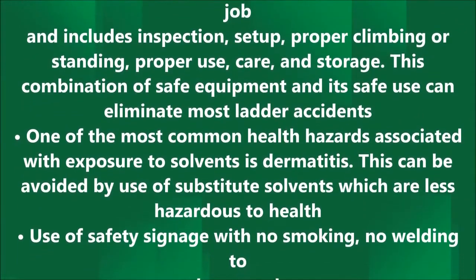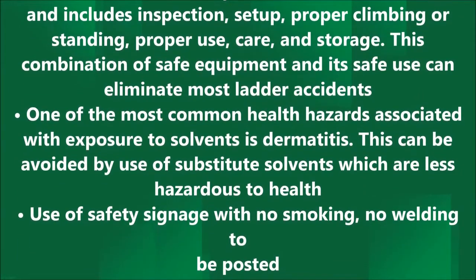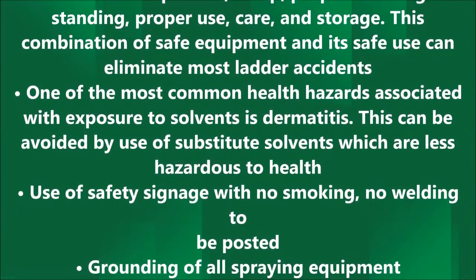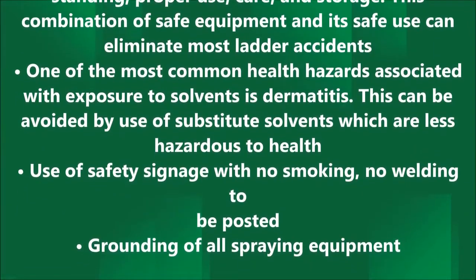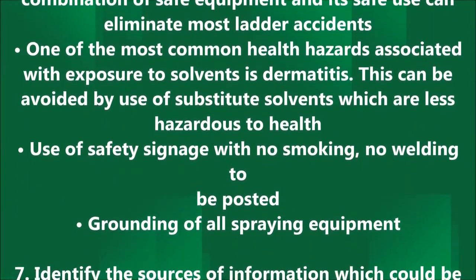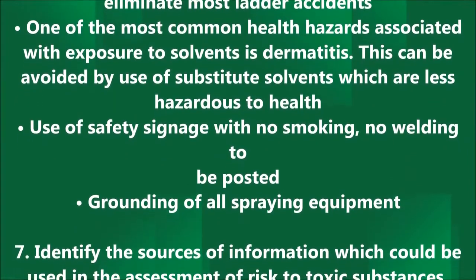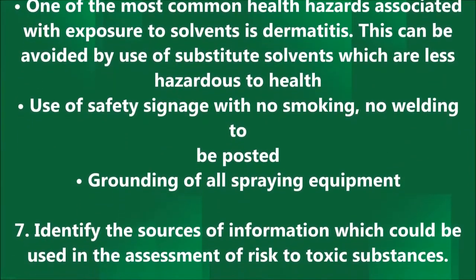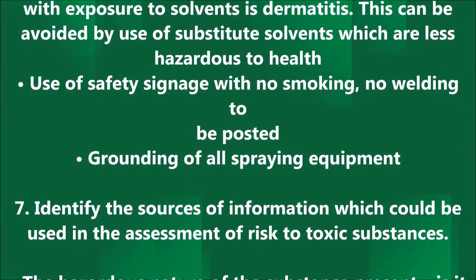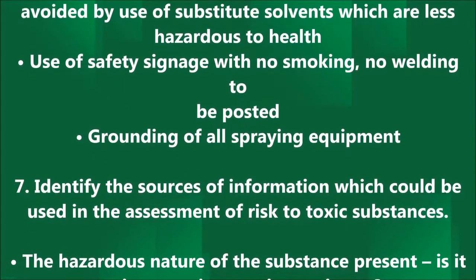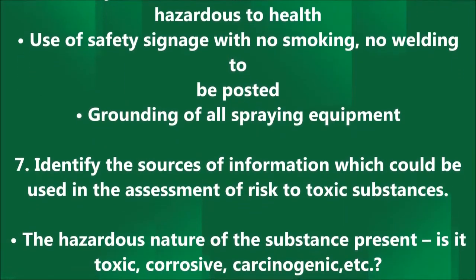One of the most common health hazards associated with exposure to solvents is dermatitis. This can be avoided by use of substitute solvents which are less hazardous to health. Use of safety signage with no smoking, no welding to be posted. Grounding of all spraying equipment.